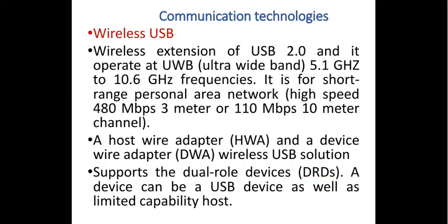You have the wireless USB supporting the dual role devices, DRDs. That means a device can be a USB device as well as a limited capability host. Again, what is the meaning of the limited capability? That all comes with the specifications as long as your communication scenario is concerned, so let us not move into those details. One which is having the capability of acting as a host, maybe with limited capability, and also as the device, definitely these kinds of devices are supported by your wireless USB.